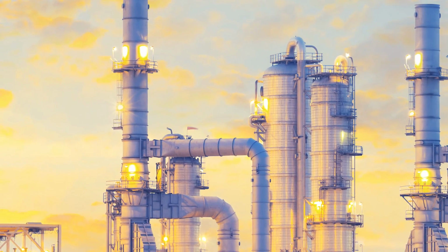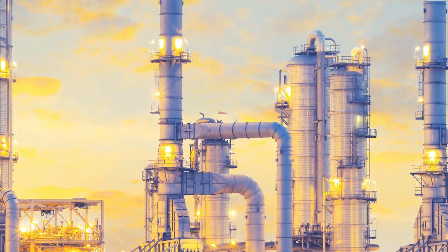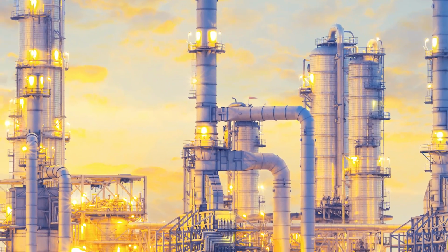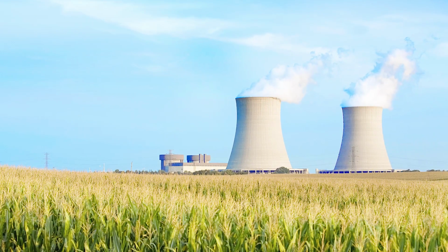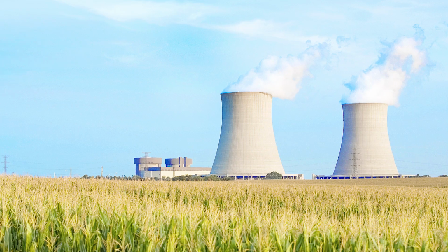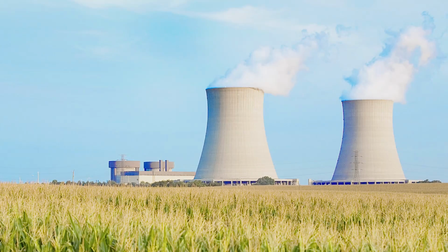Welding can take place in almost any setting, and each has its own set of challenges. For a weldment in a nuclear reactor, for example, the choice of filler materials and the procedure for welding are of course critical. And moving the welding operation underwater poses an entirely new set of problems. Should the decision be made to weld overlay the base metal? If so, with which grade? And should you weld with wire or strip electrode?